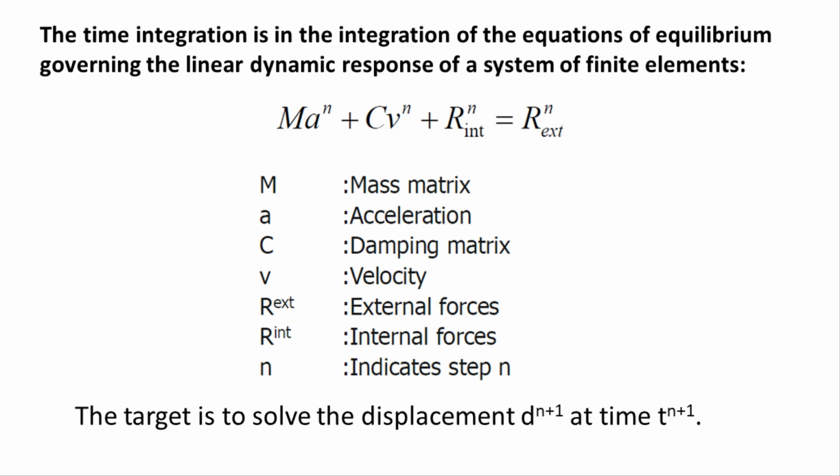The time integration is in the integration of the equations of equilibrium governing the linear dynamic response of a system of finite elements. For static analysis, the velocity and acceleration-dependent forces in the analysis are neglected. The choice for a static or dynamic analysis is usually decided by engineering judgment, the objective thereby being to reduce the analysis effort required. However, it should be realized that the assumptions of a static analysis should be justified, since otherwise the analysis results are meaningless. Indeed, in nonlinear analysis the assumption of neglecting inertia and damping forces may be so severe that a solution may be difficult or impossible to obtain.